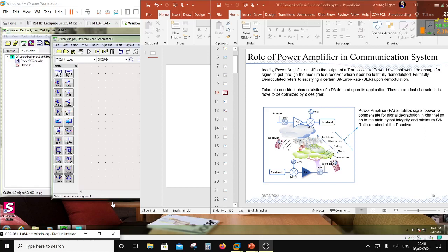So what happens is, let's say you're going to transmit a signal through a wireless medium or even a wired medium. So what are you doing? You are basically taking a signal, which is a digital signal or an analog signal, and then you are modulating a carrier frequency with that, and that carrier frequency is going to be much higher than the signal which carries the information. And then you transmit that carrier modulated signal, and then you receive it on the receiver side. This way you are going to transmit information from transmitter to receiver. So the most important part is the carrier frequency you are going to transmit, and the signal is basically modulating that carrier frequency.